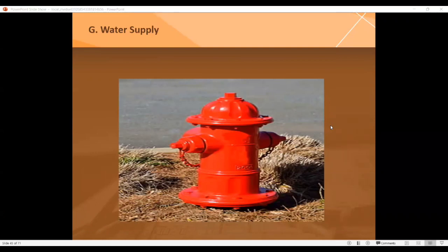All interior wet standpipes shall be connected to a straight main not less than 100 millimeters in diameter, or when the water pressure is insufficient, to a water tank of sufficient size as provided in subparagraph. When more than one interior wet standpipe is required in the building, such standpipes shall be connected at their bases or at their tops by pipes of equal size.